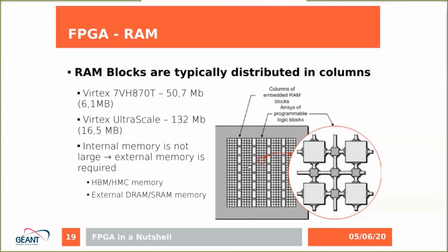If you want to implement a huge memory inside the FPGA where more blocks can access this kind of memory, then you need to also implement some memory arbitration to control these accesses. So you really need to think on the hardware level.